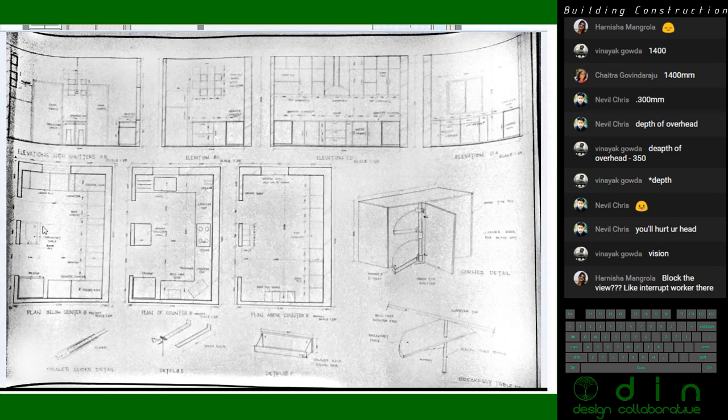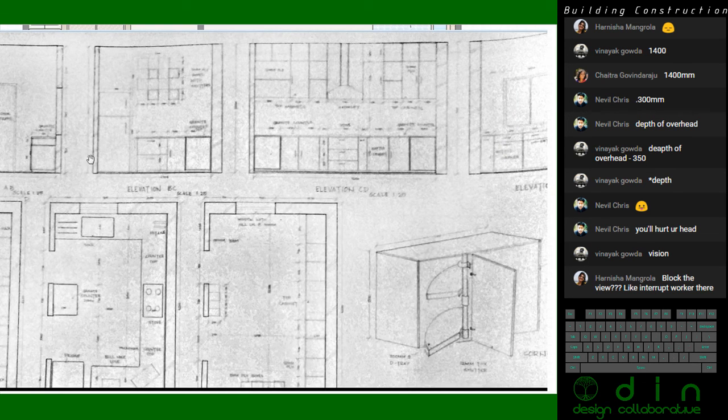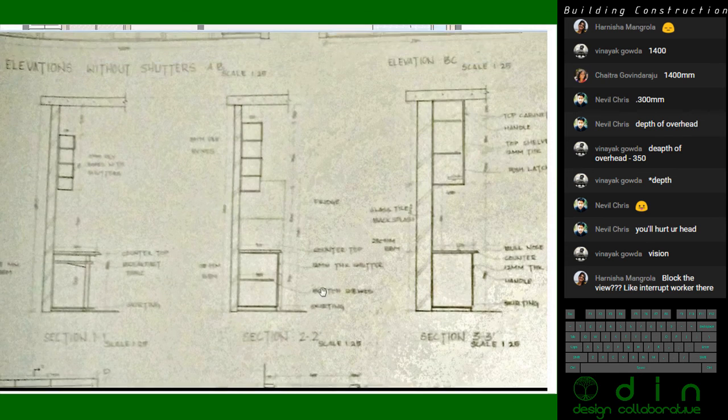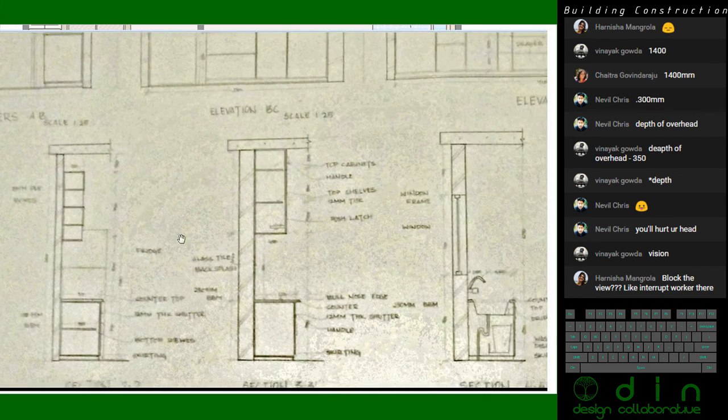Then we basically had the elevations of all four walls. So you have the four elevations showing the different things, like the chimney and how that goes out, all the shelves, any other extra design features that you want, and most importantly, they are sectional elevations, showing the counter and things like that below it. In most of the sections here, you have the floor, the skirting, the door in front of the shelves behind, possibly a drawer, and your above counter wall units.